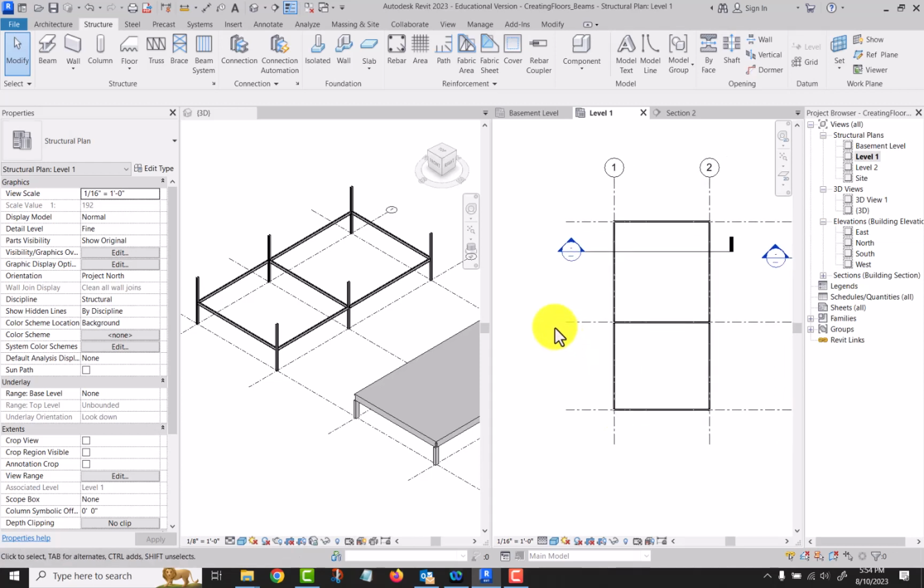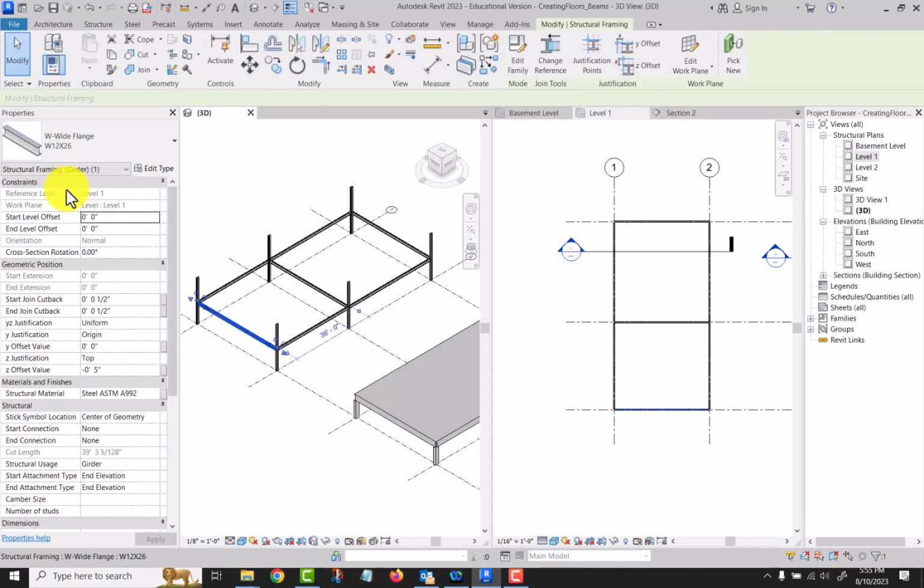If you're placing beams and you forget to do that offset, just like we did with the concrete ones here, you can pick it and change the start and the end offset elevations after you place them right here. And this is useful for if you have a sloping beam for whatever reason. Yeah, parking garages is an example where you have sloping beams, okay? Or maybe you have a beam on the roof and you need a slope, so that's that.